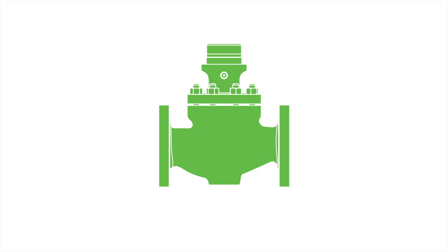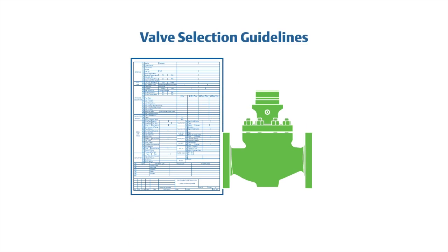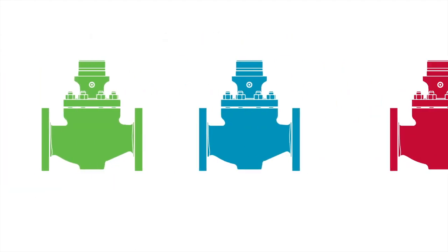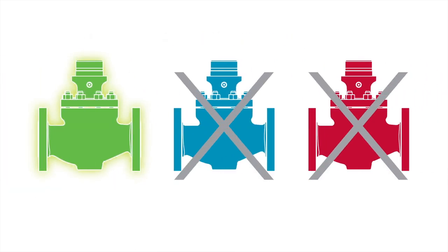What we need to keep in mind is once we do get a control valve flow coefficient, we need to use the manufacturer's suggested guidelines for selecting the proper trim for that control valve. You don't want to mix one manufacturer's selection criteria with a different manufacturer's, because chances are the principal operation of those two different control valves are going to be different. So make sure to keep with the manufacturer's selection guidelines for that specific valve vendor.